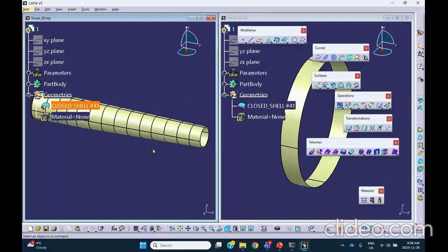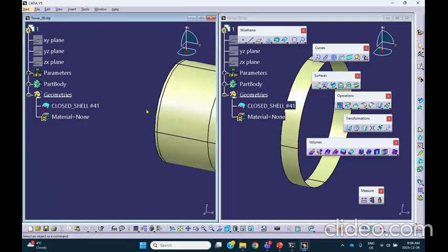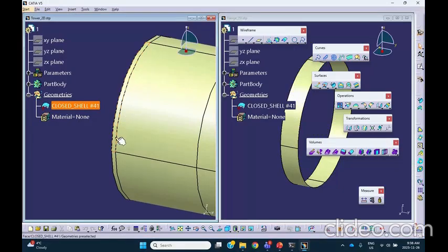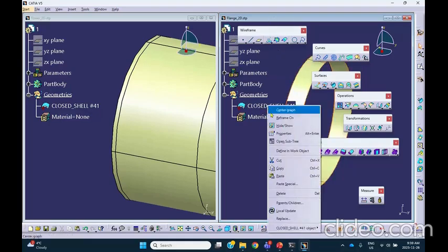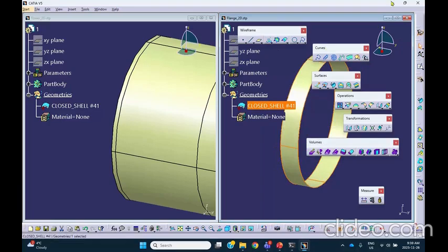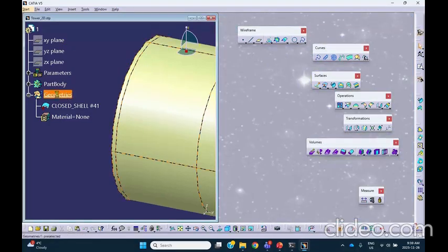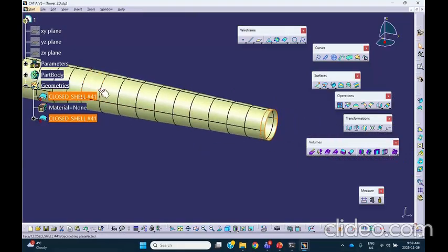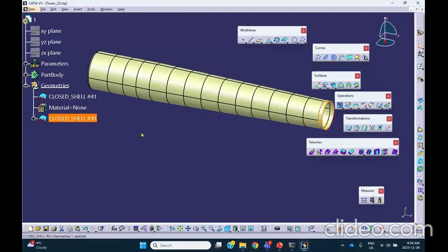Okay. So that piece at the end of the flange, at the end of the tower that I was talking about, are these pieces, which I'm going to get rid of in a minute. Now, I don't want to work with two files, so let me copy this, go to here's the flange, copy this, and come here and paste it into the geometrical set. So notice that I now have the tower over there, and the flange right here, which was copied and pasted. Okay. All right.